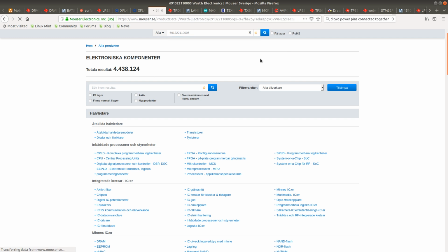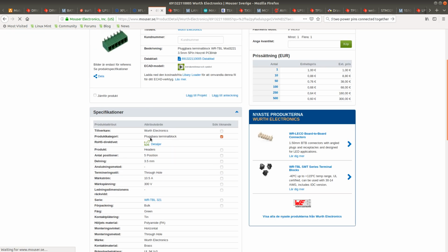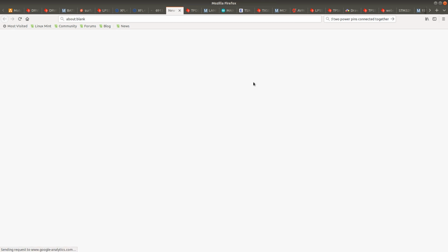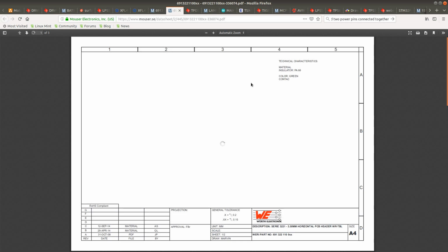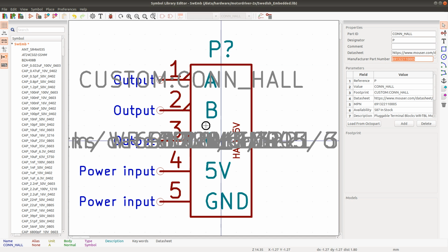So it could be that I have correctly designed the footprint and made it a little bit smaller because it has to stick out 5 millimeters, but I want to just double check it. So 9.2, and if we just remove 5 millimeters, it's going to be 4.2.